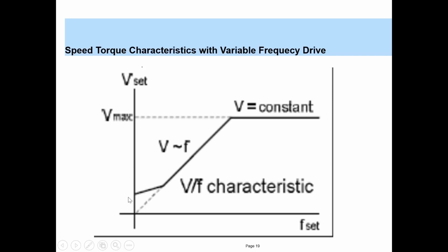So this voltage is sufficient to generate the amount of torque to move the drive, to move the motor initially, and then you increase voltage and frequency in a constant proportion up to the base point.